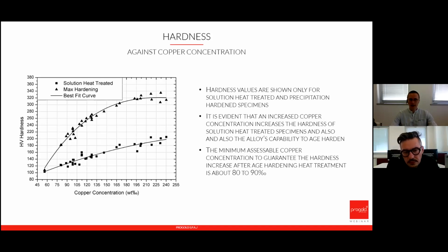To answer your question, we can say that the grain size will be bigger for the case of the lower cold deformation. For example, you say 60 or 65, I don't remember. Anyway, if you deform the material more, during the annealing process the grain size will remain smaller because you deform it more.